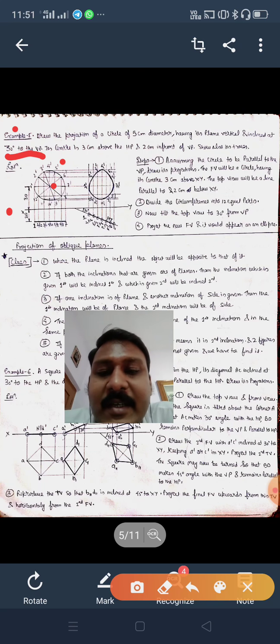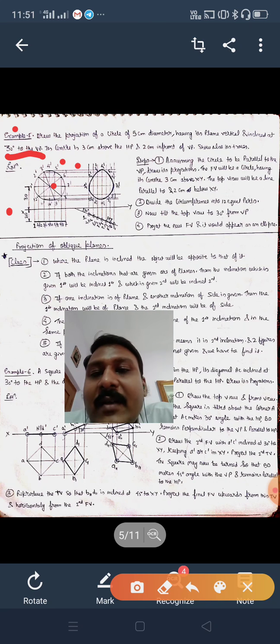The circle has 360 degrees. Divide by 12, it means 30 degrees. So keeping the protractor in the center of the circle, mark 30, 30, 30, 30 at the top. So these are the points. Then extend the points, joining toward the center to the bottom, and then you will get the circle divided in 12 equal parts.